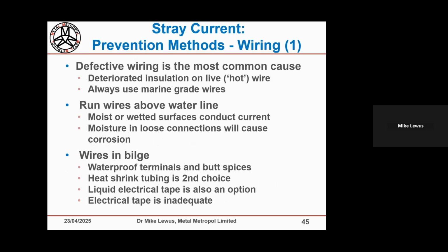And it's probably worth adding that wires in bilges, particularly where insulation has been undermined or degraded. So live wires in bilges is a classic. Sometimes it's a result of electric bilge pumps, loose connections or poor connections out of sight in a bilge pump, causing current to flow in bilge water. And immediately the most serious component ready to be attacked are the keel bolts.